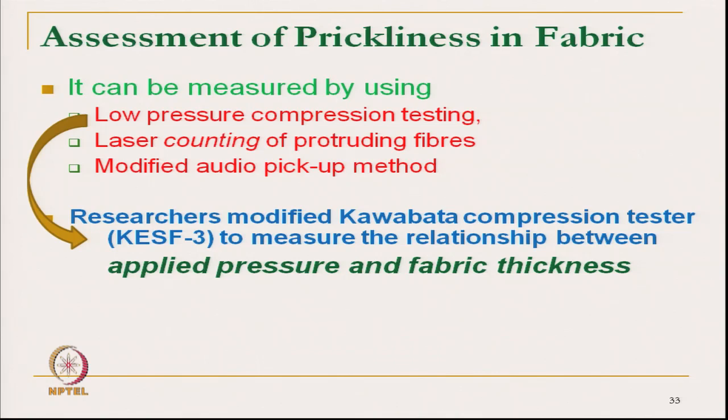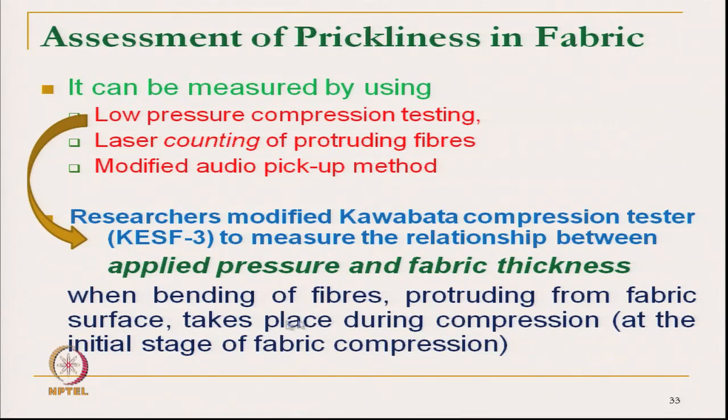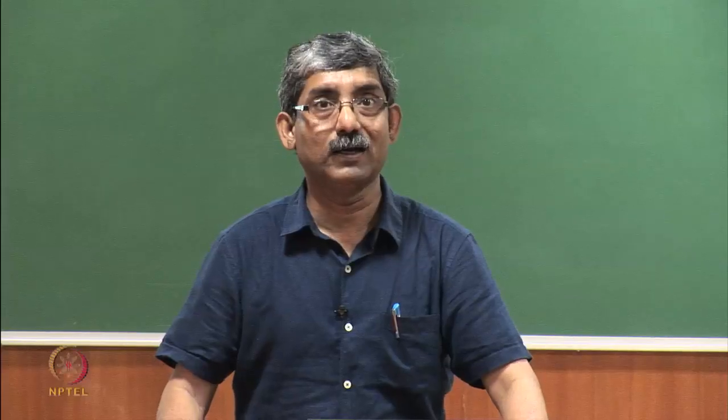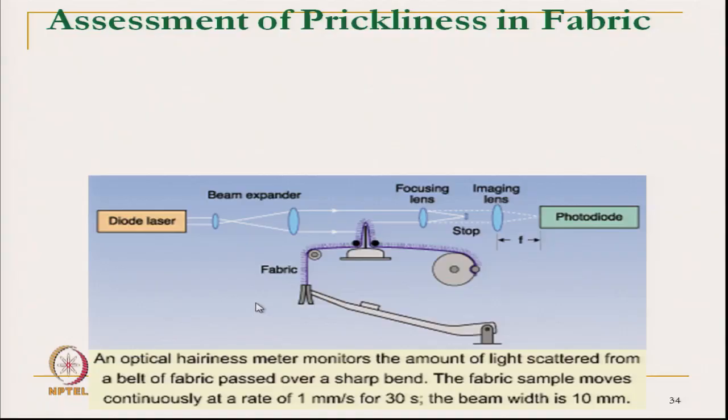So, the relationship between applied pressure and fabric thickness, that we can measure. So, when bending of fibers protruding from the surface takes place during compression, at that time we can get an idea of the hairiness or prickliness by the low pressure compression system.